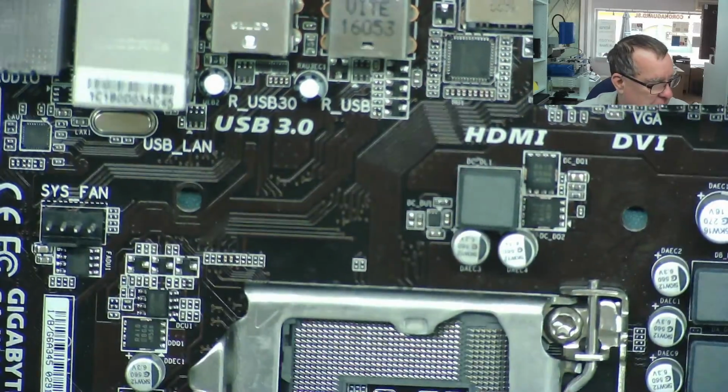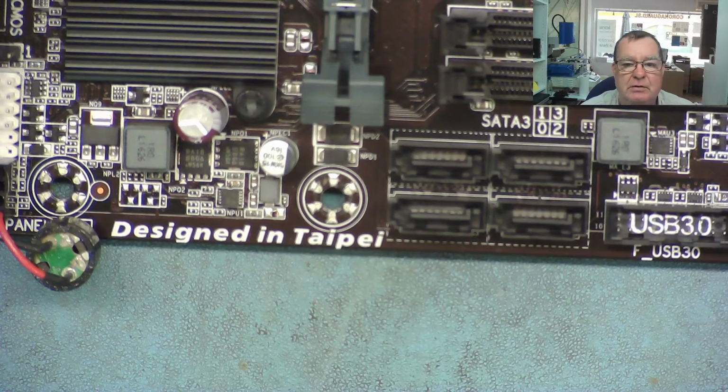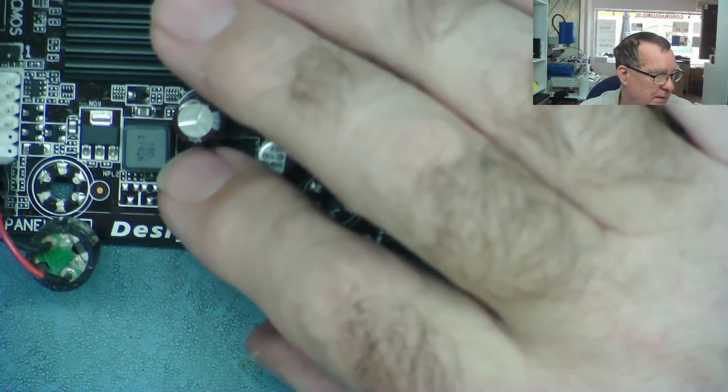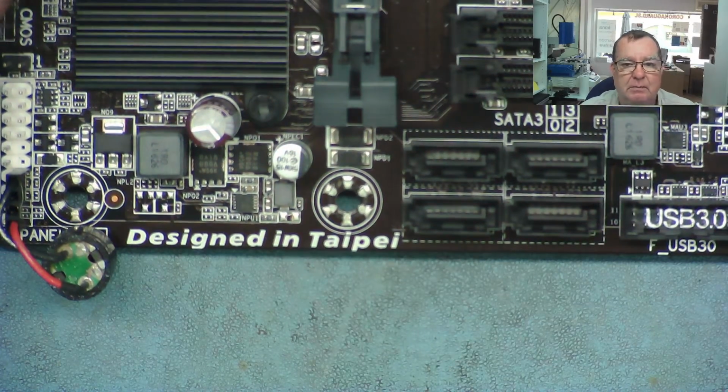These don't have any markings at all. There is a list of these markings and the actual values, and I'll link that in the comments below so you can look up what these are. But I'll tell you now, the ones that are marked like 1R0, that's a 1 microhenry. So 2R2 would be a 2.2 microhenry inductor.